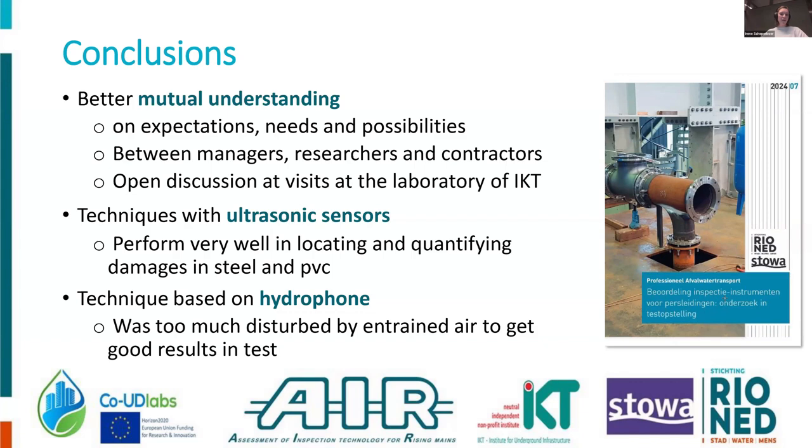That was because of the entrained air, which blocks all other signals, so it is difficult or impossible to detect defects that are behind these air bubbles. So the test setup was not really suitable for this technique.